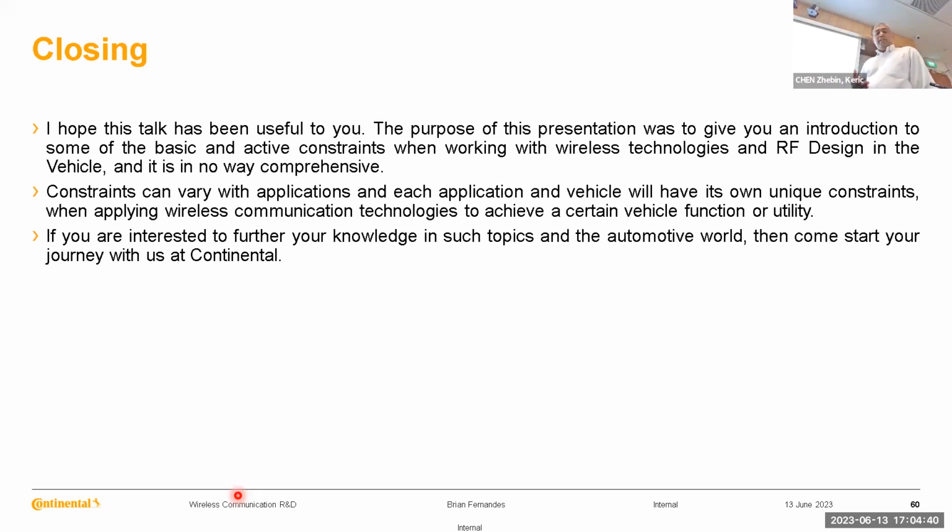So typically in cities, in a lot of countries, the tunnels have GPS repeaters, so that the GPS signal is received from the satellite and then directed into the tunnel. So there are GPS, or GNSS, repeaters in a lot of these tunnels. You may still see some shadowing effects. It could be temporary if the car is moving very fast, but it could also be permanent if your car is stalled in a tunnel.